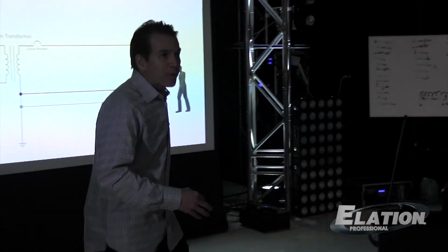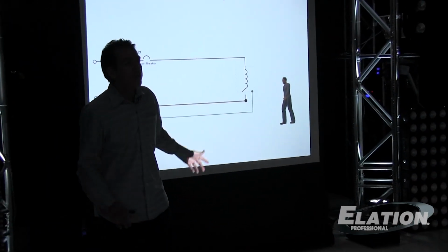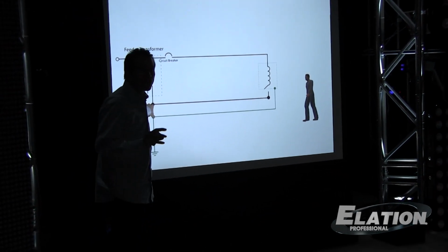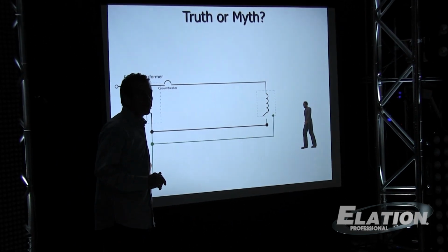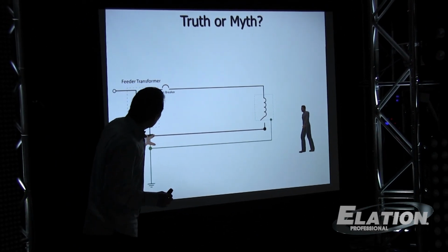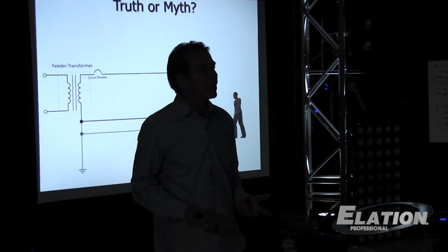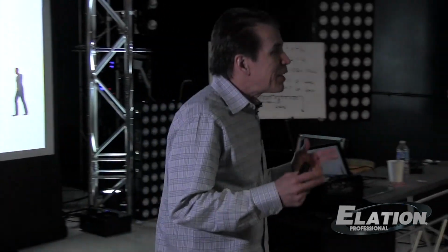And remember, what's the voltage of the earth? Zero. So the voltage right here has to be at 0 volts. We're forcing it to be at 0 volts. So if you meter between the white and the green, what should you read? 0. In theory, 0 volts. That's not always the case.